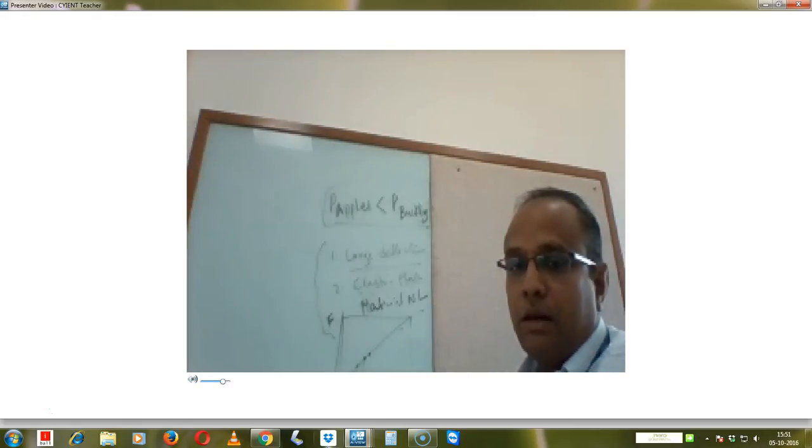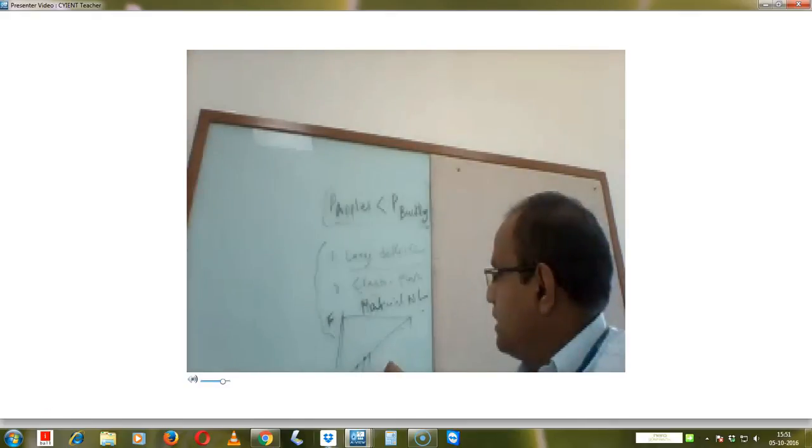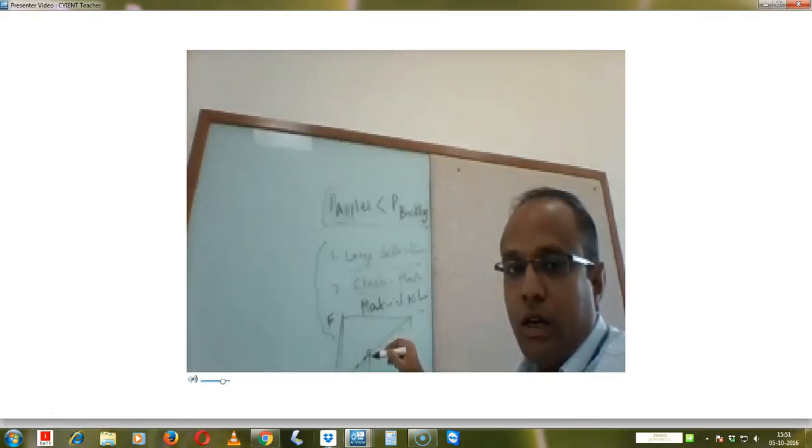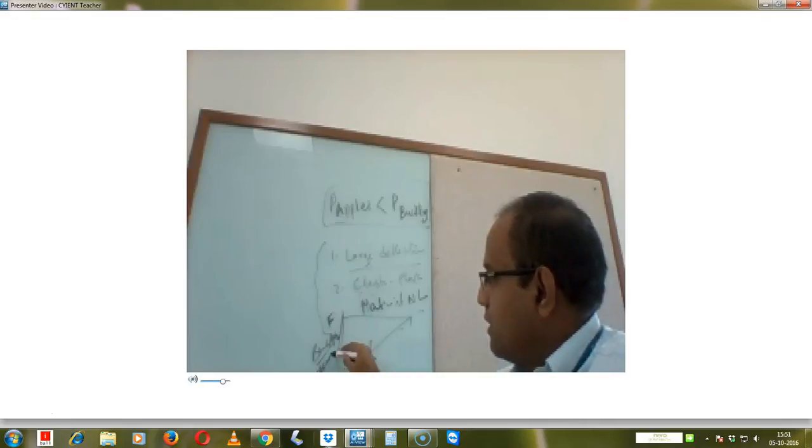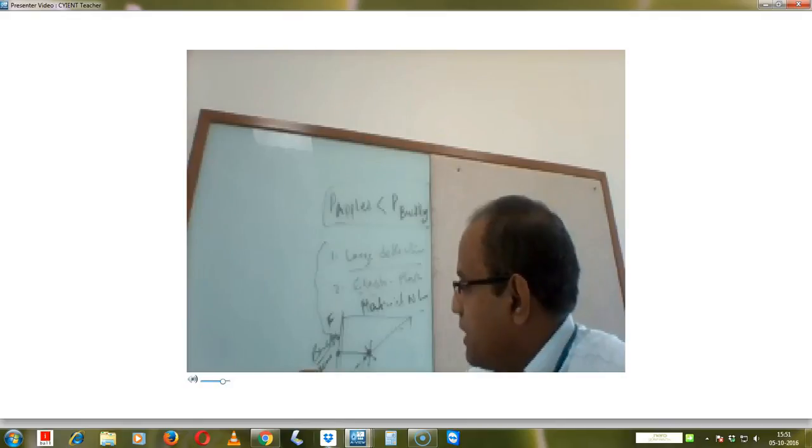Why the divergence will happen is because there will be a change in the large deflection. There will be very high deflections. That means even small load application will cause very high deflections. That's where instability will happen. So it will stop at that location. Okay, so that load will be our buckling load. That will be checked with the operating load, and that will give the buckling load back.